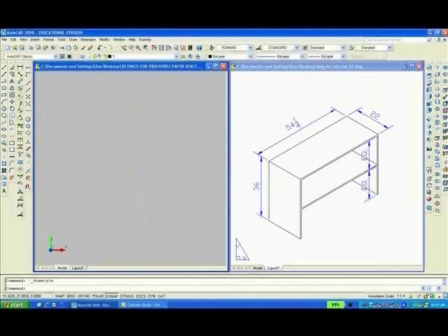In addition, we want to change the crosshairs, so I'm going to click on Snap. Nothing happened, so I'll type the word SNAP, enter. Then I'll type S, enter for style. I want to change the style of the snap to isometric, and then I'll type I, enter.